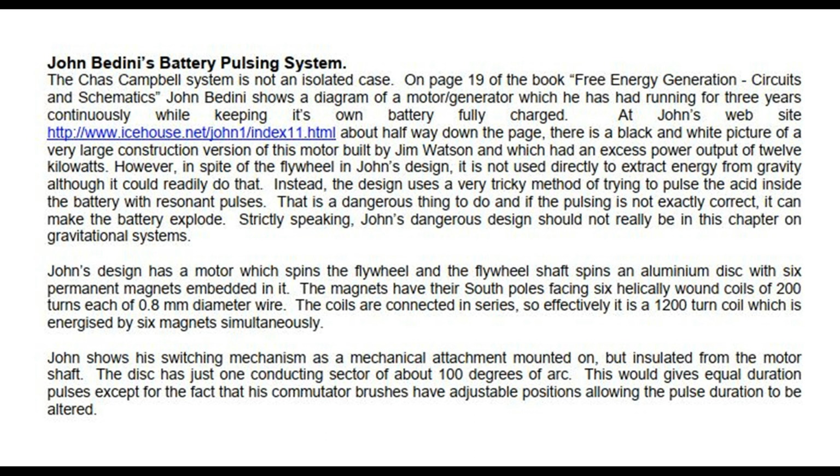John's design has a motor which spins the flywheel, and the flywheel shaft spins an aluminium disc with 6 permanent magnets embedded in it. The magnets have their south poles facing 6 helically wound coils of 200 turns each of 0.8 mm diameter wire. The coils are connected in series, so effectively it is a 1200 turn coil which is energized by 6 magnets simultaneously.